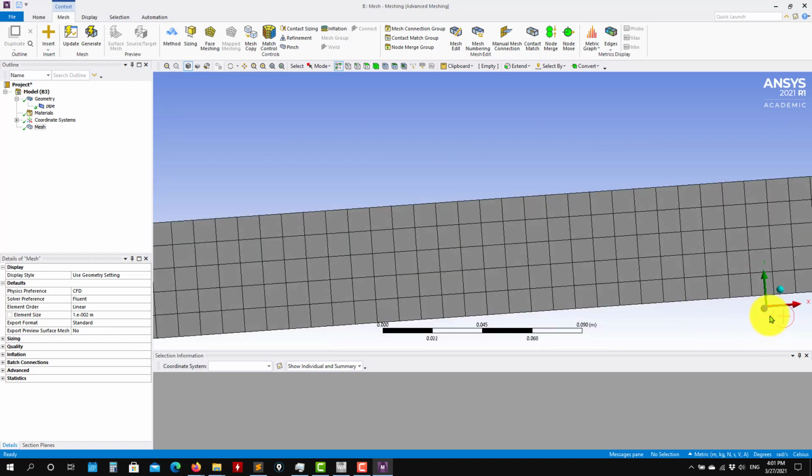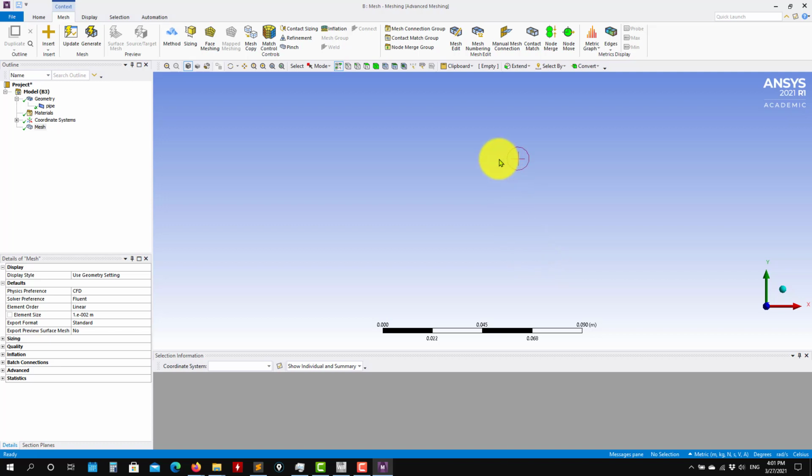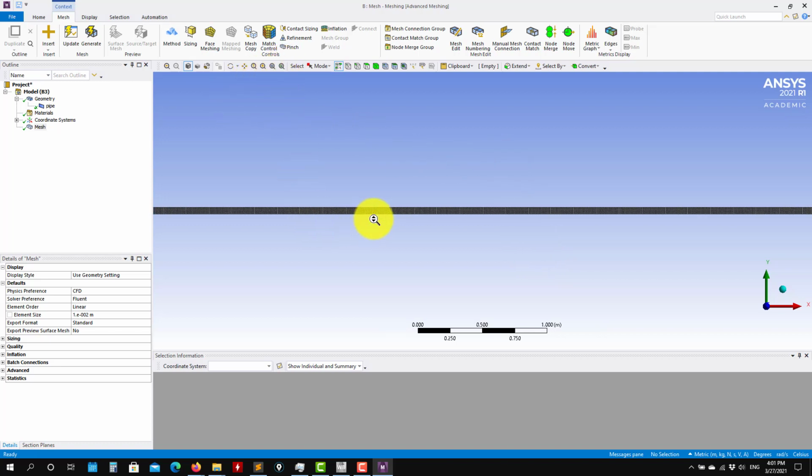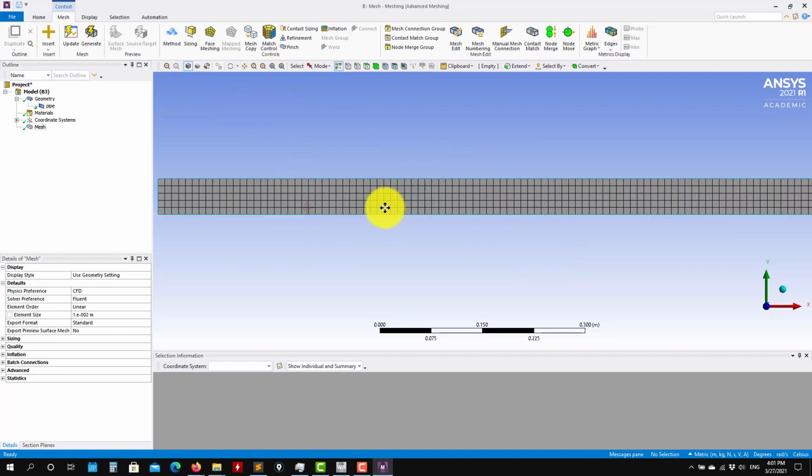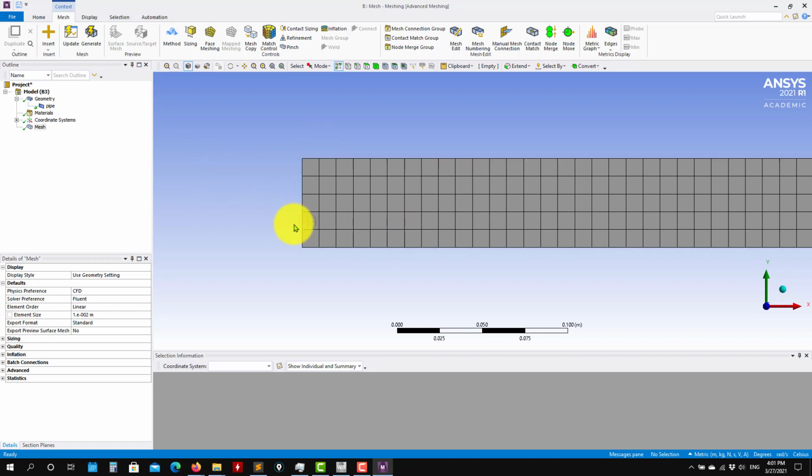And when I talk about a structured mesh, it's basically this. So let me fit to screen here. It's that the meshes are uniform. Okay, they are quads or hexes, and they are uniform. So these are the best cell types that you can use in CFD, but sometimes for industrial applications, it's very difficult to get something like this. But don't be afraid about using triangles. They work just as well.